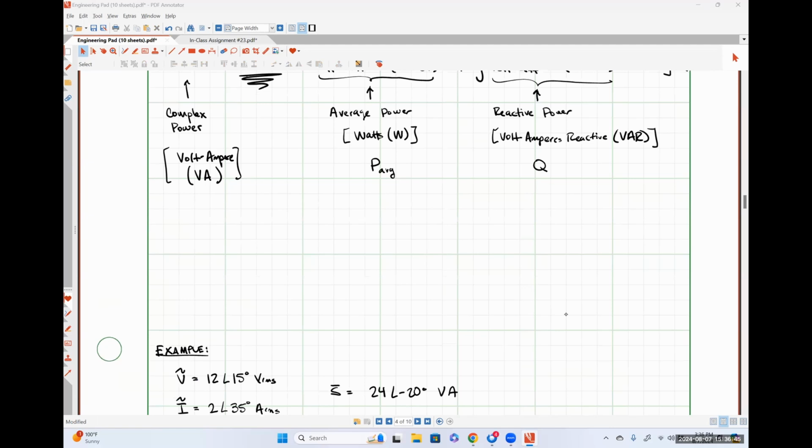What do I do to find the conjugate? So you can have your calculator do the conjugate operation for you. That being said, the conjugate of a complex number, all that means is you change the sign on the imaginary part for rectangular form complex numbers, or change the sign on the angle for polar form complex numbers.